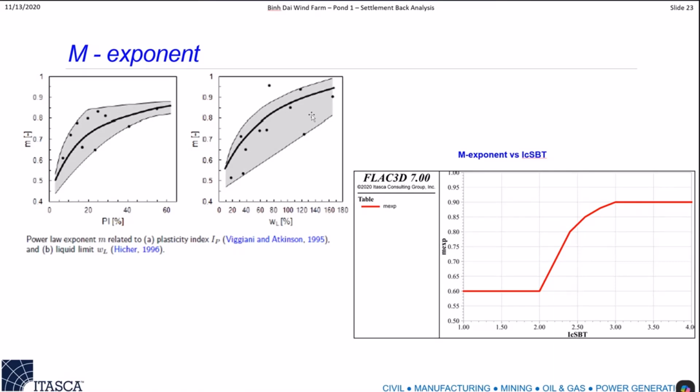As you have seen, even for this project, I had tons of lab data, tons. I just didn't look at all of it. Besides the physical properties, the value of the lab data is in the physical properties, for example, the measure of the density, the measure of the void ratio, the liquid limits, so physical quantities that are useful in terms of soil characterization or classification. But as far as the mechanical parameters, they are a little bit better for the shear strength, but when it comes to the deformability, especially at scale, the lab data are, in my experience, essentially not applicable.